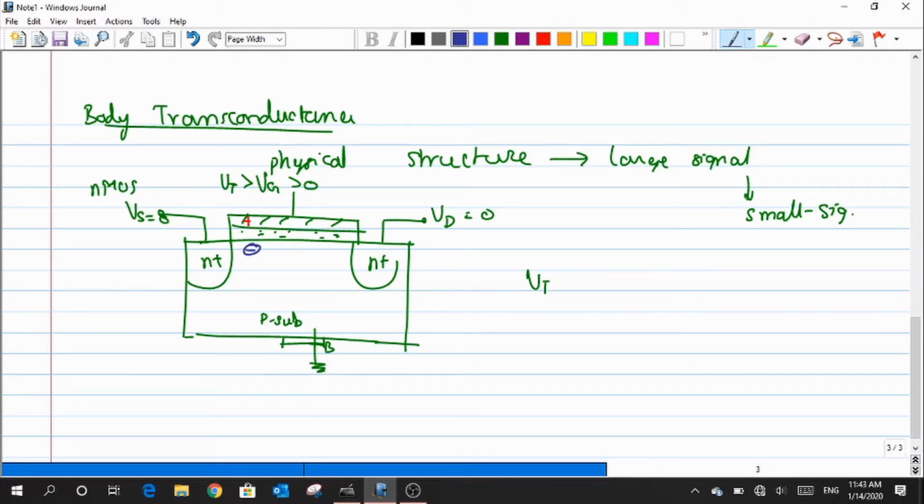Am I right? Yeah. So now I'm going to vary this VG all the way closer to VT, but still not equal to VT. Which means I'm trying to place more holes on the metal plate, due to which it has tried to deplete the charges here. I have to have a similar number of holes in order to have this, right? Yeah. So now I'm going to call these the depleted charges, QD.